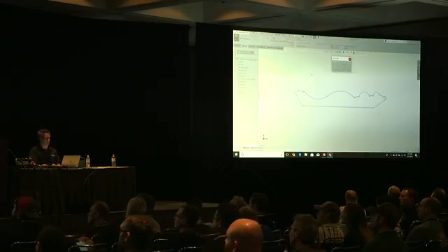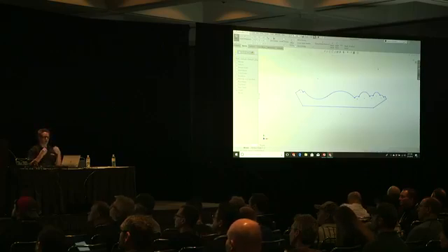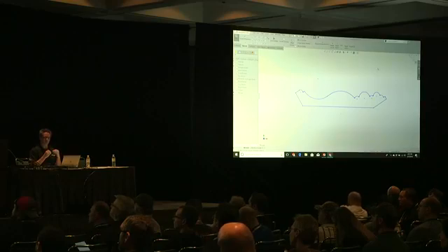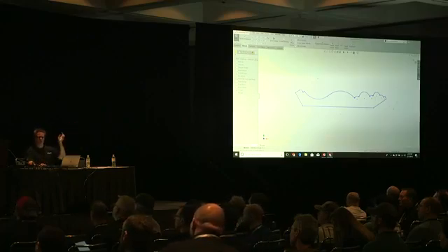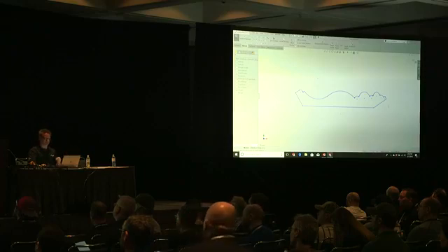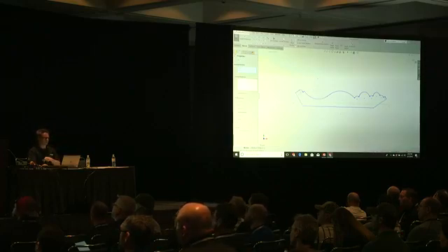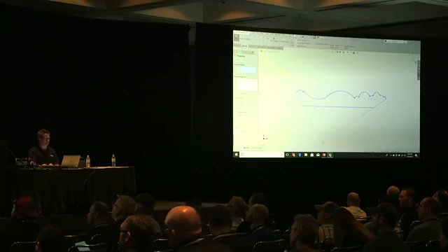Use one of my standard part templates. There it is. I'm not going to use 2D to 3D. And a lot of what I'm going to do here is going to seem weird, but it will make sense at the end. You've been warned. So everybody knows left to right window, everything inside the window, right to left, anything that it crosses. Select two lines, you hit point, it's going to give you the apparent intersection.